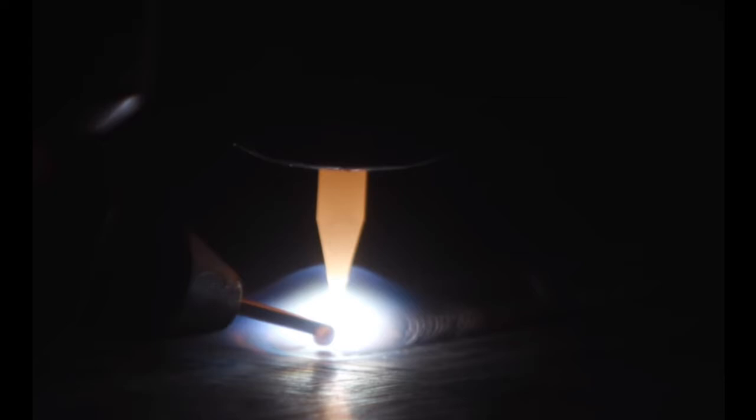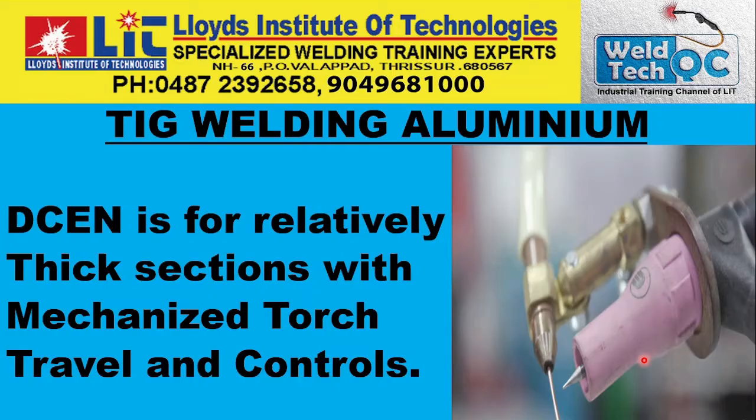You get a deep, narrow penetration and excellent current carrying capacity of the electrode. DCEN is for relatively thick sections with mechanized torch travel and controls. Generally used for mechanized TIG welding, and rarely used for manual TIG aluminum welding.